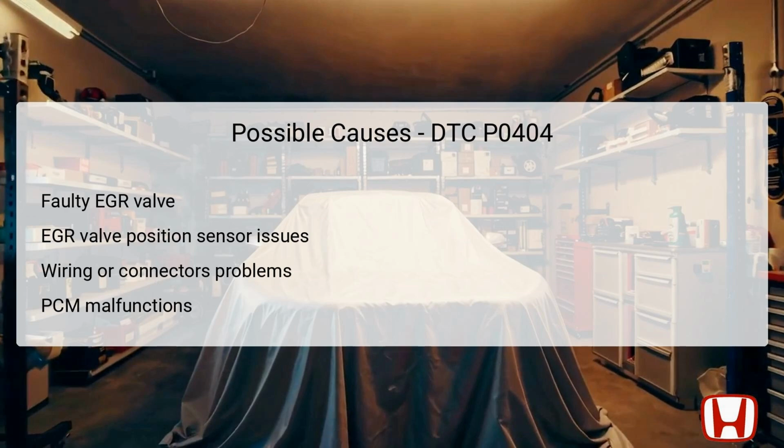Additionally, the integrity of the wiring and connectors should be investigated, as damaged or corroded wiring can interrupt signals between the EGR valve and the ECM. Lastly, though less common, malfunctions in the powertrain control module, PCM, might also cause misdiagnosis of the EGR system performance.